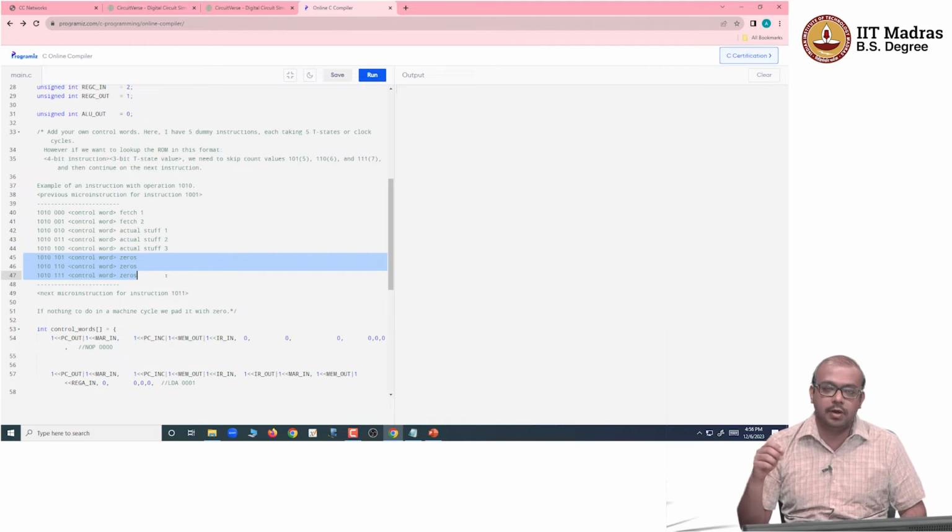If you remember, I told you about 3 levels. The naive thing is just to have a counter that counts from 0 to 7, so every instruction is going to take 8 clock cycles. And I know that none of my instructions take more than 5 clock cycles, so that is definitely a stupid thing to do. One thing we can do to make it better is to have a ring counter that starts from 0 and always cycles through 5 states. At least that saves you 3 states, so 5, 6 and 7 are never touched by the processor.